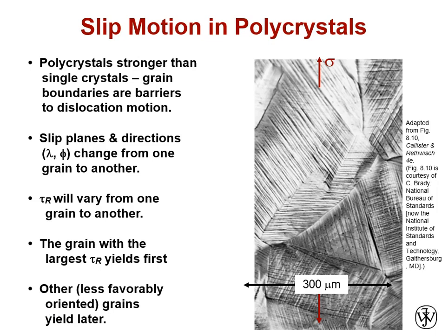So in general, the grains with the largest resolved shear stress, like we just said, will yield first, with another weighting factor for those for which you have easy to move systems also lined up with your resolved shear stress. Again, this is reiterating that favorable grain orientations move first until all of their dislocations basically pile up at the grain boundary, then the others move.